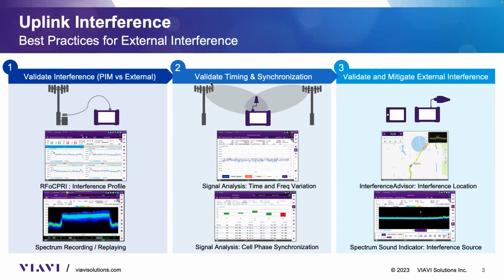If we have a problem with time, then we're going to have interference, due to the fact that the radios are transmitting frames. They should be transmitting roughly at the same time. Certainly, there's a little bit of time to compensate for propagation delay. However, if there's a radio that is out of sync, that gap allowed for propagation delay is going to be exceeded, therefore causing interference, with the downlink overlapping with the uplink.